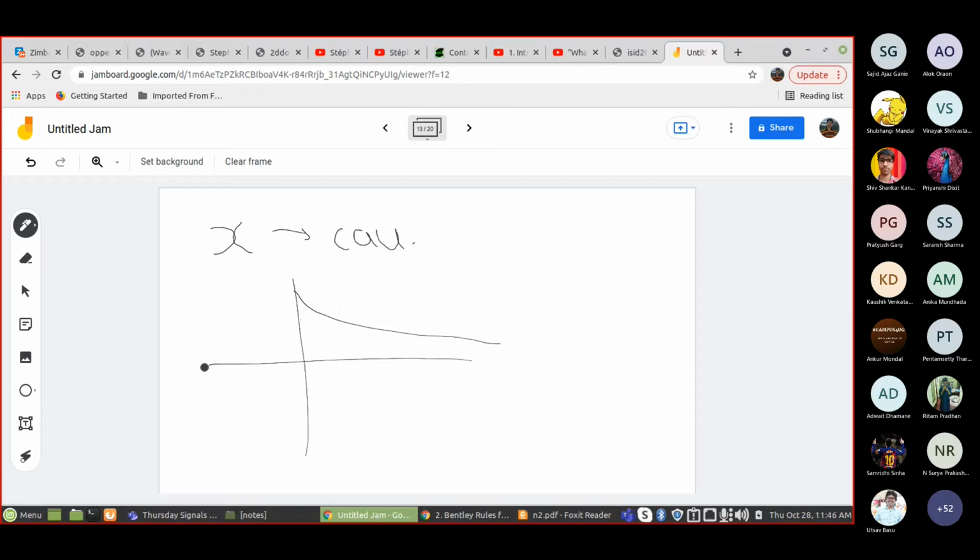For an exponential you have t identically 0. So this is in time domain, and this is the signal x, for example. The signal is identically 0, but ROC is not with respect to time domain. It makes no sense that ROC is right or left of something; ROC makes sense in the S domain.